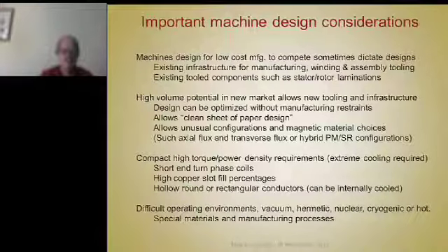A lot of times, an obvious example is that for low-cost manufacturing, the manufacturing people, purchasing people, and sometimes management, they want to use cheap magnets and cheap laminations, and they want real low slot fills of copper in the windings to make it easy to wind and not have any failures and have a very high throughput. But you see, there's a price to pay for all those low-cost aspects.